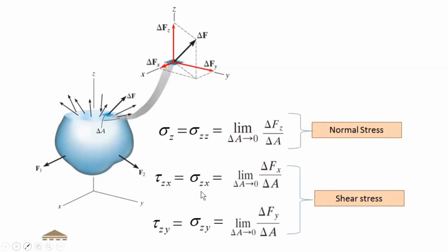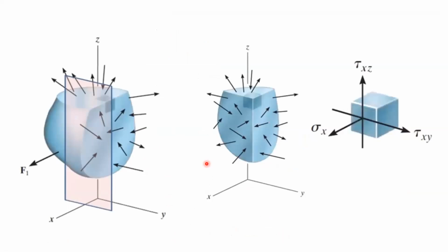Okay. So we moved ahead and we have taken one more section. Then there are again some internal resisting forces. We have done it one more time, and finally we have got something like this, a cube. In this cube, basically we have considered three faces, but all the faces are like mirror images of it. So on all six faces we get three stresses acting. But when I say sigma x is acting here, the same value of sigma x is also acting in the opposite direction. Okay.